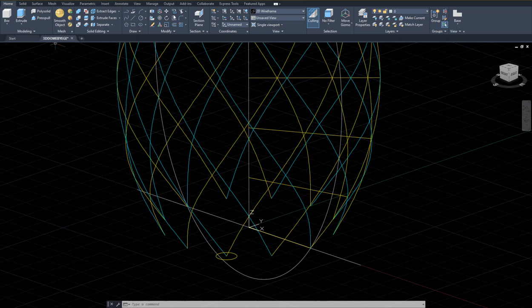So we need to have 2 copies in the same place. So I'm going to copy the circle here. And from the point where it is, the displacement would have been the same point, basically. That's going to be shift 2, 0, 0. Meaning that you're making 2 copies on top of each other. I made 2 copies of the circle. And why did I do that? Because there's going to be 2 extrusions from the same point.